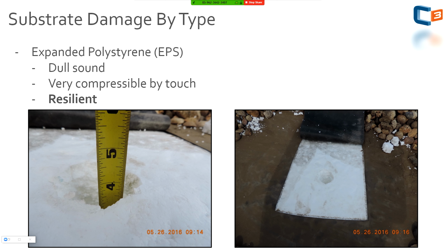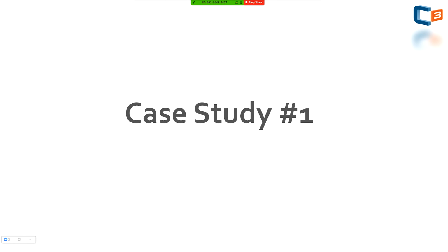And a lot of times what happens is you have seams be compromised over time through expansion, contraction. Like that is a real thing. So it does occur. But it causes leaking in sporadic areas. So every time we've come into these, a lot of times we'll see a common reported thing of there's leaking in my building, right? The owner's like, oh, there's leaking. It happened after the hail loss. And we might interview different tenants, and they'll be like, oh, it's been leaking for 30 years, and we're like, red flag, that doesn't look good. So again, these are just very difficult roof systems and difficult substrate types.